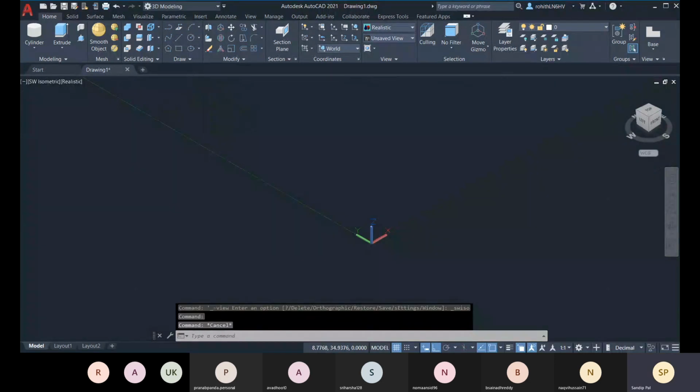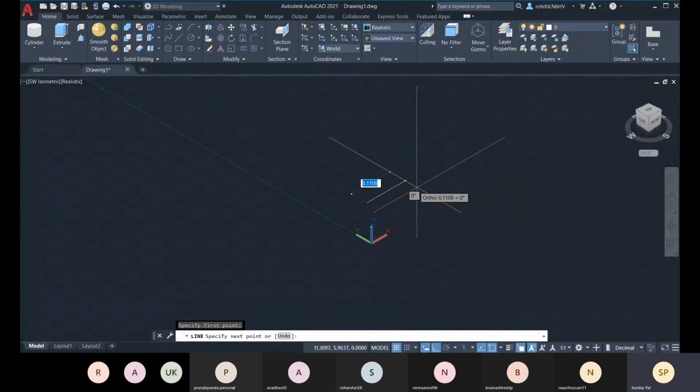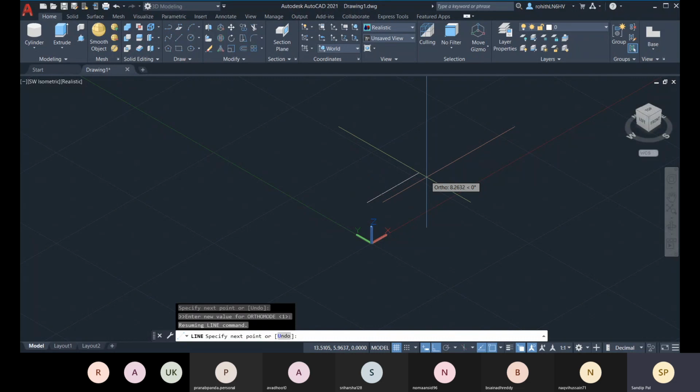Okay, now see that this is the origin, means this is the center point right now. So at the rate, then you will provide the radius value so that you can place it at any angle. So let's go with at the rate and 2, and then you can provide either 0 degree. So let's go with the 0 degree first, and then at the rate 90 degree. So let me show you that and enter, and that I have created.